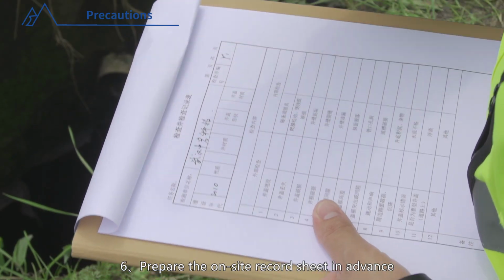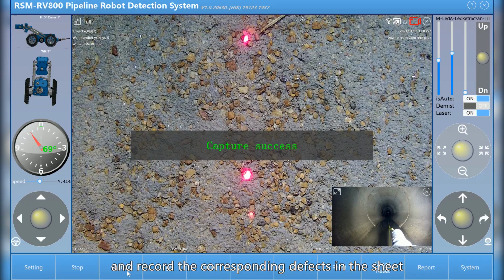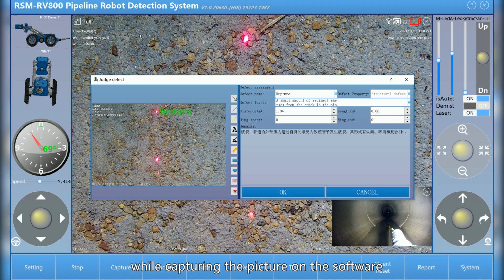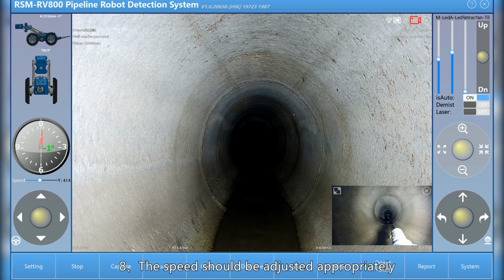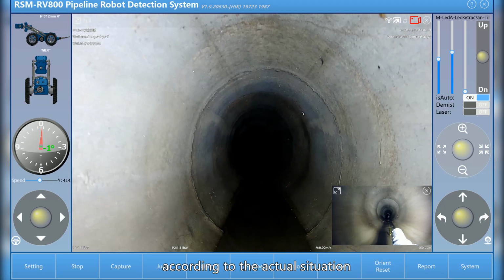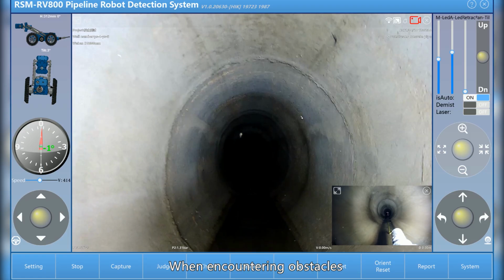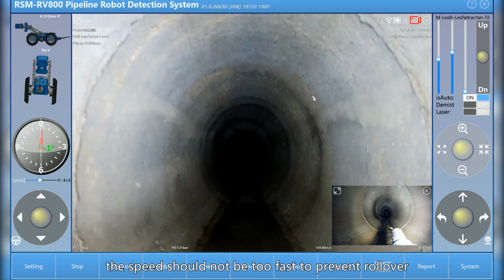6. Prepare the on-site record sheet in advance and record the corresponding defects in the sheet while capturing the picture on the software. 7. It is necessary to do a simple test of the various functions of the instrument before downhole testing, especially to check the air pressure. 8. The speed should be adjusted appropriately according to the actual situation. When encountering obstacles, the speed should not be too fast to prevent rollover.